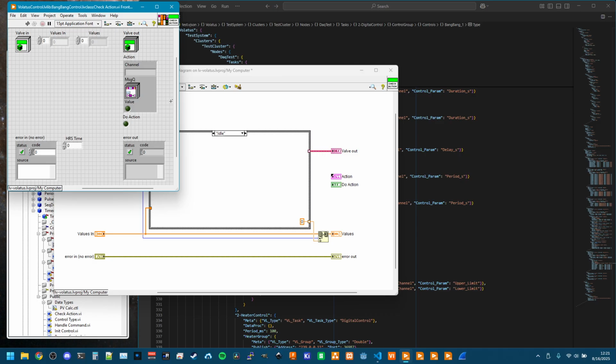And we don't want those potentially getting updated at different output intervals. We want them all updating together as much as possible. That is automatically handled by the digital control module. All this component needs to do is let it know, hey, do you need to send a command? And if yes, what's the channel name? What message queue does that command get sent to? And is it a true or a false value for that digital command?